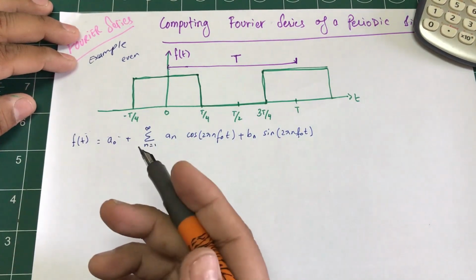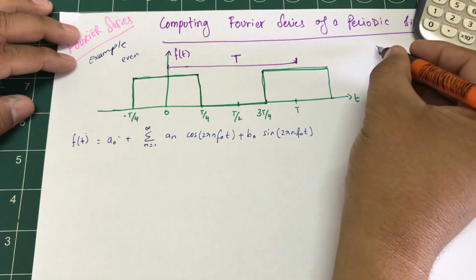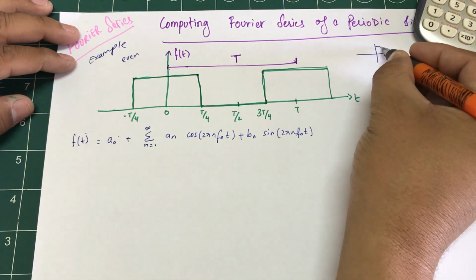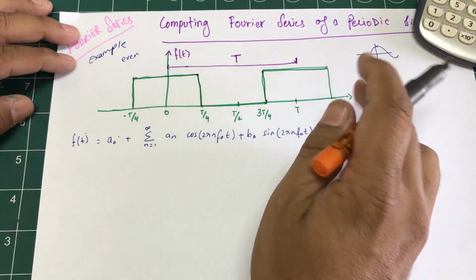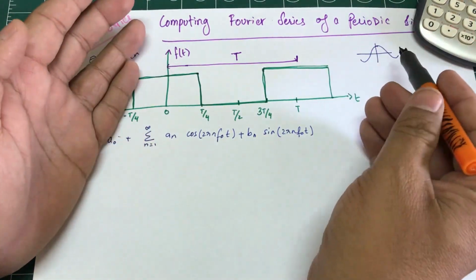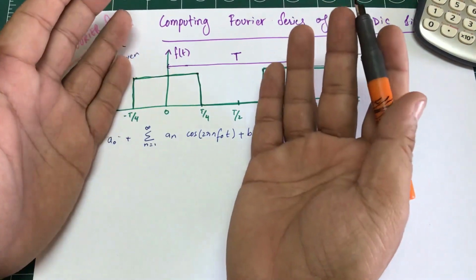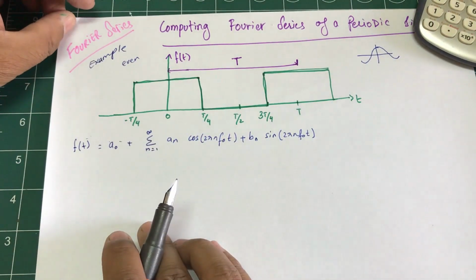And the same thing, look at a cos signal. Is cos an even signal? Definitely it's an even signal. Why? Because cosine starts something like this. If from the middle I were to fold this, considering this a sheet of paper, this would lay on top of the other one. So this means this is an even signal.